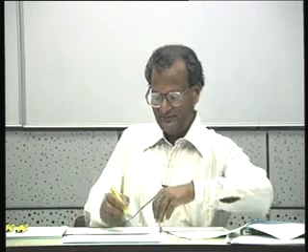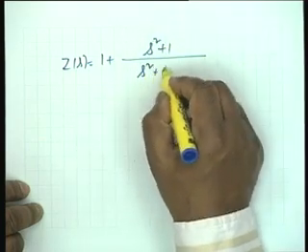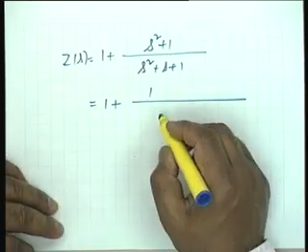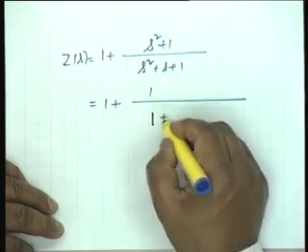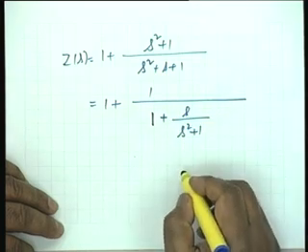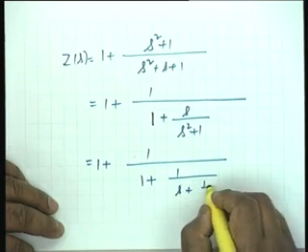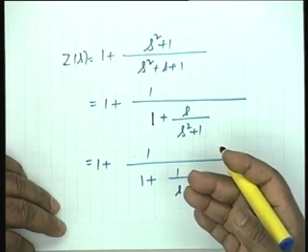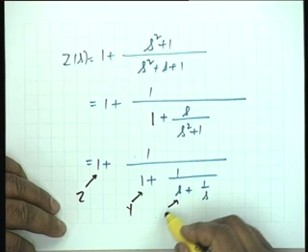I have to synthesize this. Now some tricks of the trade. What I have is z of s equal to 1 plus (s square plus 1) divided by (s square plus s plus 1), and one should be able to see that I can write this as... divide by s. No, I don't divide by s, I divide by s square plus 1. So I get 1 plus s divided by s square plus 1, which I can write as 1 plus 1 by (1 plus 1 over s plus 1 over s). Don't you see that I have expanded into a continued fraction, and I have done this by inspection. Now since this is an impedance function, this is impedance, this is admittance, this is impedance, this is admittance.